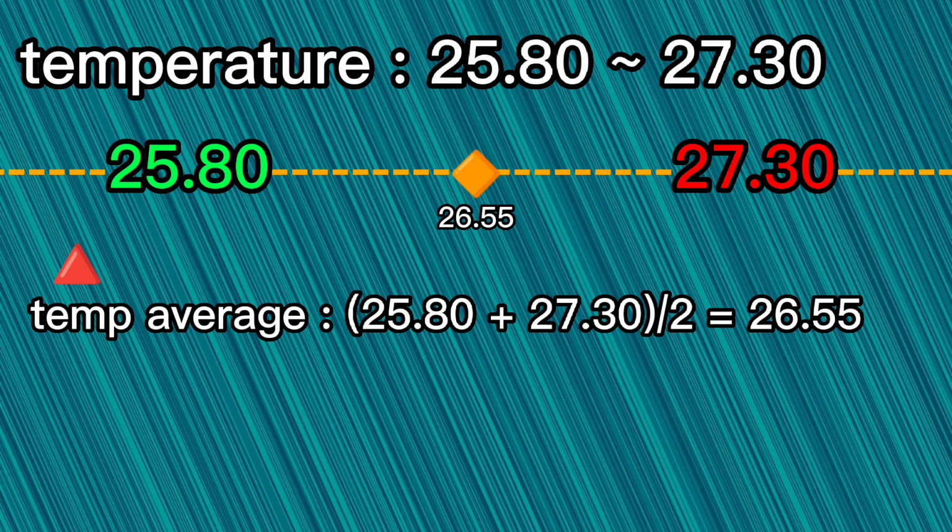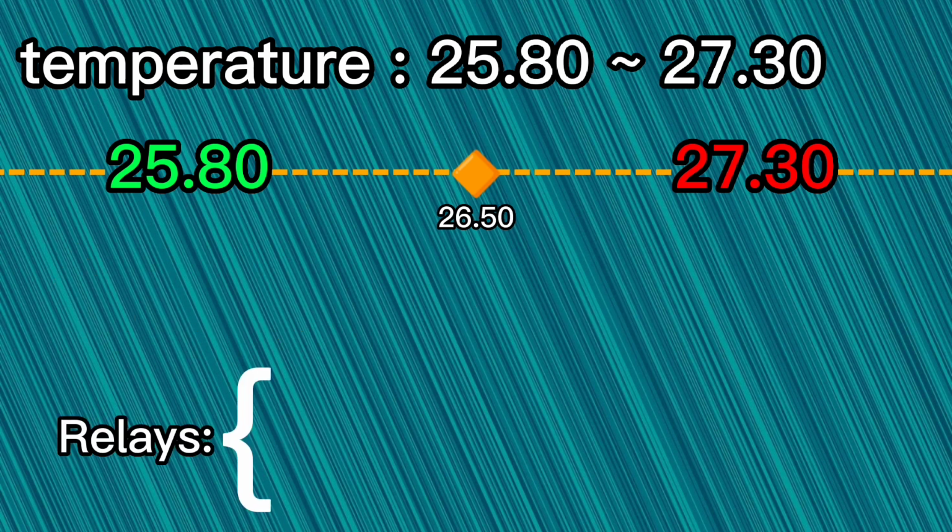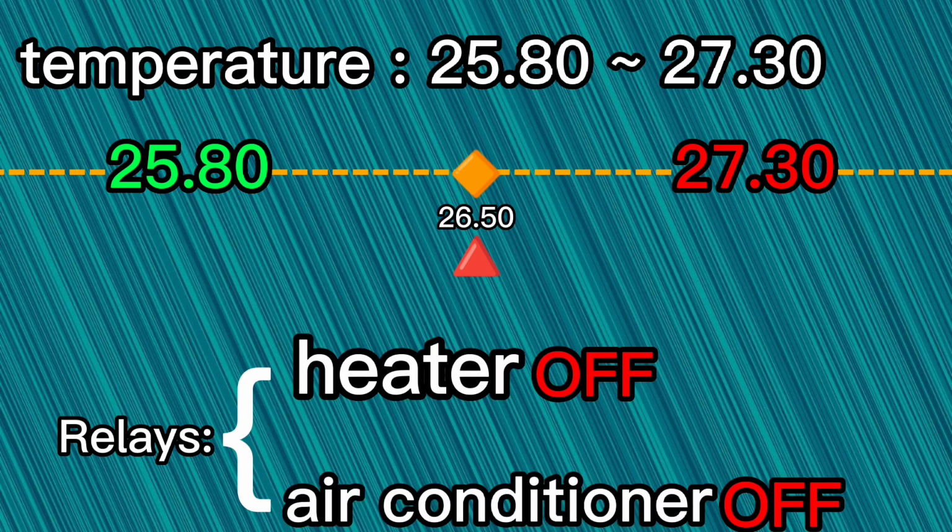The sensor I used in this project is the DHT22, which has a measurement accuracy of 0.1. The calculated average may have two decimal places, which causes the program code not to recognize this number. To solve this problem, inside our code, we convert the calculated average number to a number with 1 decimal place. When the temperature increases and reaches the average temperature, the heater turns off and remains off until the ambient temperature drops below the minimum temperature.